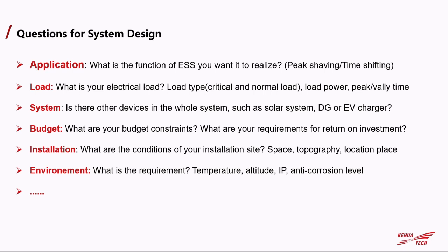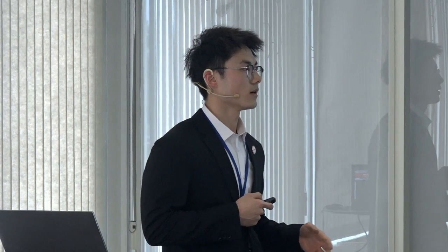And also we need to know the load power, the peak and valley time of the load. When is the peak time and when is the valley time, the peak hour and the valley hour, because this determines the capacity of the energy storage system, and the capacity also involves the budget, the cost of the energy storage system.